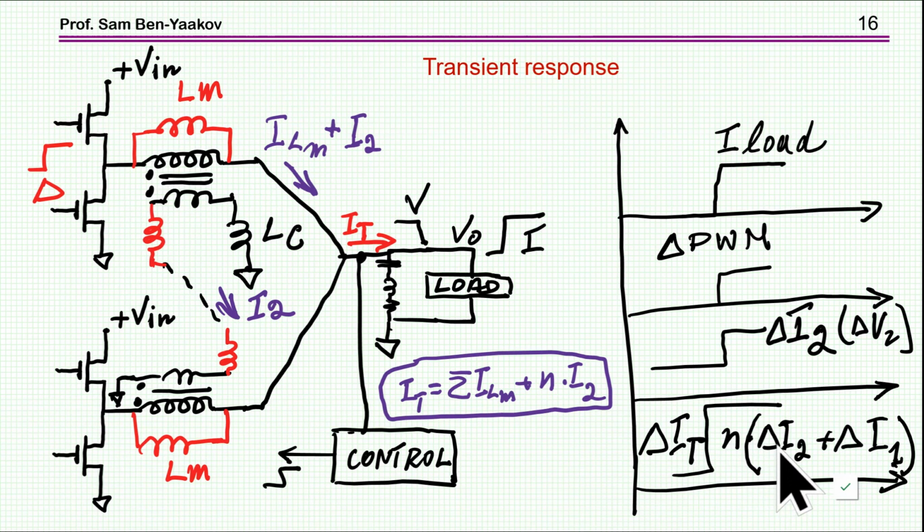And then n times this change in the secondary, which is here in series, and here it is in parallel in all of these. So there is sort of, you might say, an amplification effect, that the series current here is now reflected as a parallel current, so therefore you're getting a current which is n times larger than the current here for a one-to-one configuration.